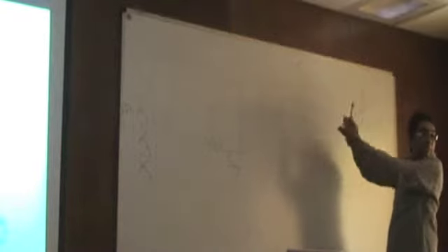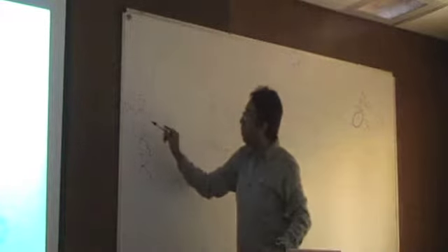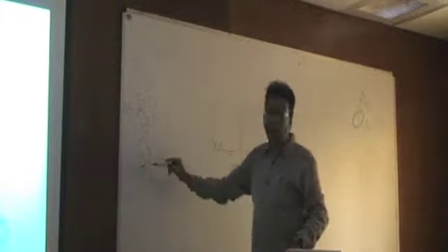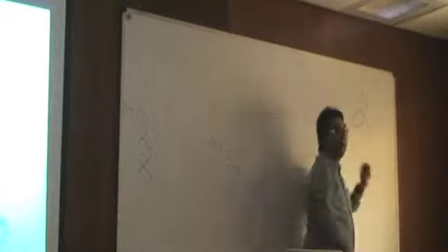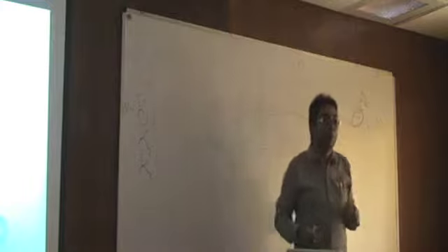So the bending stiffness that you're interested in relates this bending moment with the curvature. In other words, it's a relationship between your kappa 2 bar or kappa 3 bar, whichever direction it is. In this case, the bending moment is about x2, so it's kappa 2 that you're looking at.